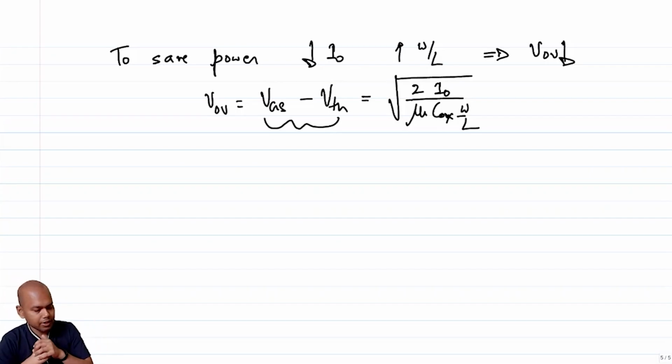you can think of it in this way: if the transistor is not on and you are trying to swing the voltage at the source while keeping the voltage at the gate fixed, then in one half cycle you are trying to push the transistor more into subthreshold. In the other half cycle you are trying to make the transistor slightly more on, right? So essentially you are going to get different response from the transistor at the positive half cycle and the negative half cycle, which means that if you give a sinusoidal input, your output current will not be sinusoidal, which means you are going to get some sort of distortion.